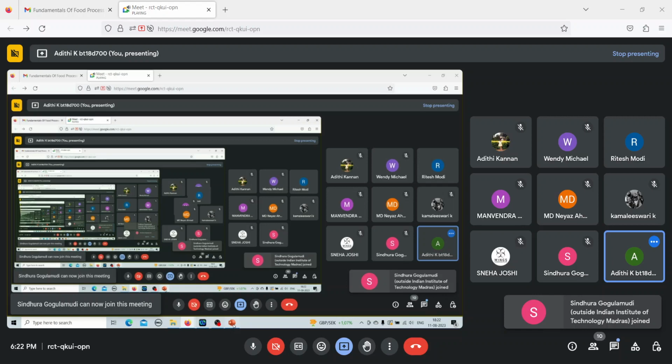Then, as I mentioned, F naught is equal to sigma L delta T. Since delta T is constant, we can take it out of the summation, which is equal to 5 minutes, into summation of L, which means you will add up all these L values. If you add up all these L values at each and every time point, then you get 0.865. So 5 minutes into 0.865, which is delta T into summation of L, will give you F naught, which is equal to 4.325 minutes. Is this clear? Is there any doubt in this?